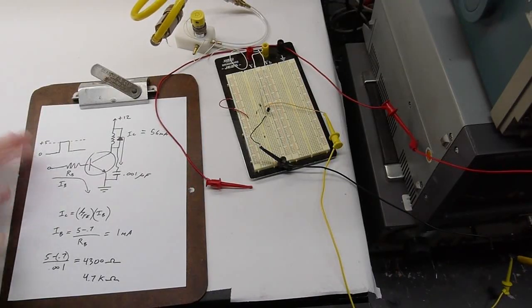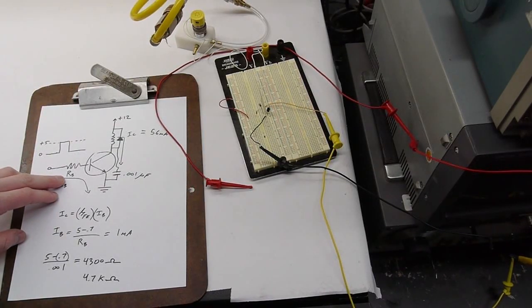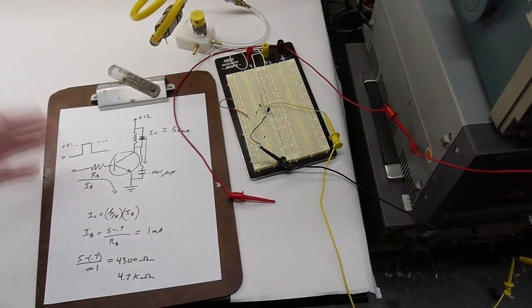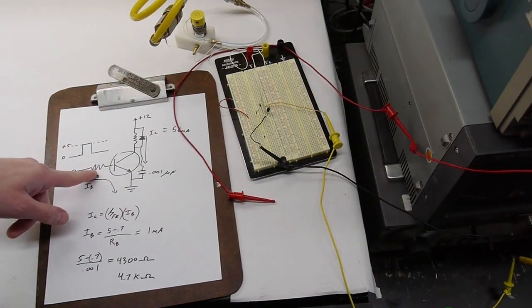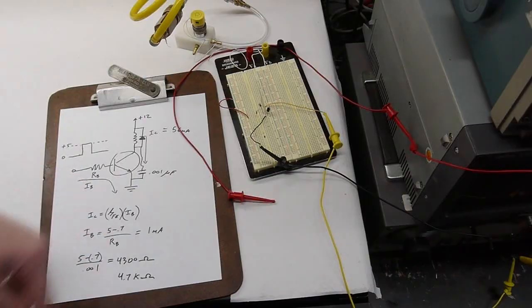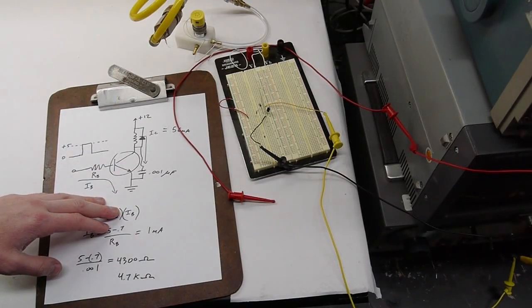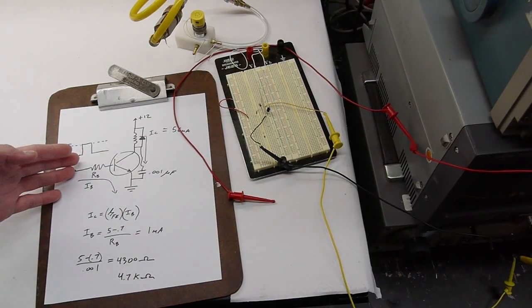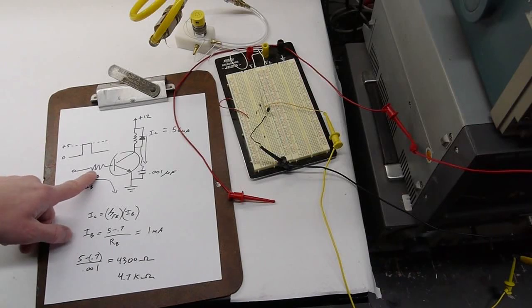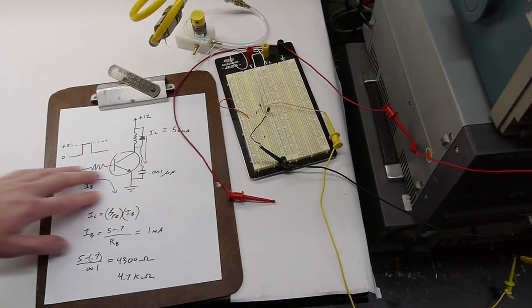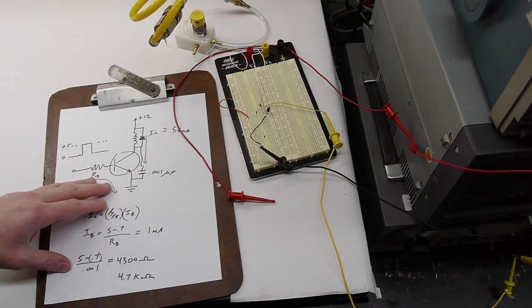So I thought of just a couple of other things you might be wondering about. Throughout this, I was kind of trying to get the base resistor value chosen, and you might be thinking, well, screw it, we'll just put a 0 ohm resistor, we'll just short this thing out and make sure we have enough base current. But unfortunately you can't do that because the transistor will draw so much current through the base it will destroy itself. So you have to have a resistor here, or else the transistor will self-destruct the very first time you use it.